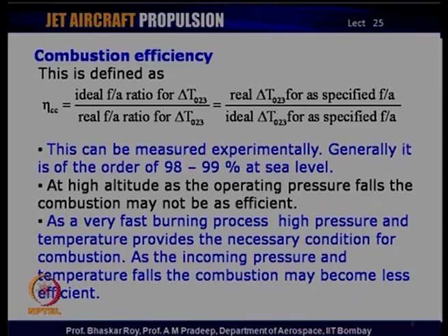this is something which is pretty much acceptable, because at very high altitudes your absolute values of pressures are likely to be lower. However, at that high altitude your thrust requirement from the engine is quite often lower. So, slightly lower burning efficiency may just be acceptable, because your fuel flow or fuel consumption, the absolute values of fuel consumption, are lower.